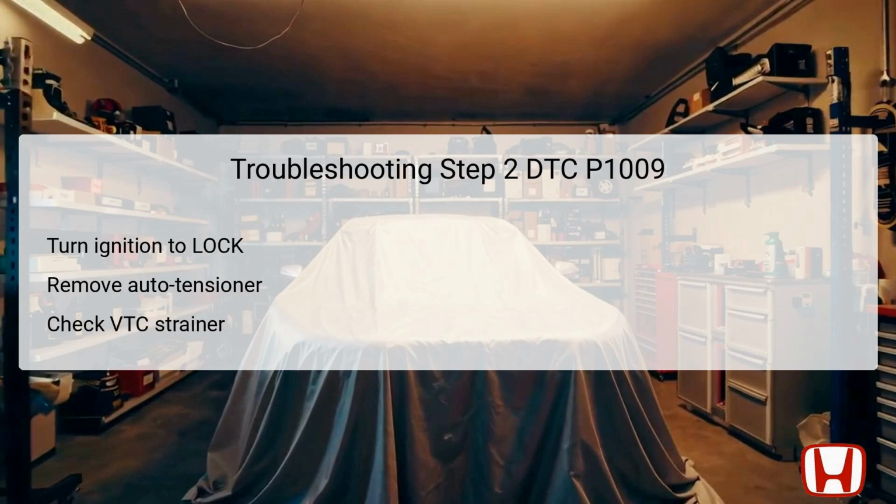For this next step, turn the ignition switch to the lock position to ensure safety while working on engine components. Remove the auto tensioner that secures the serpentine belt. This will give you access to the VTC strainer located above the oil pump.